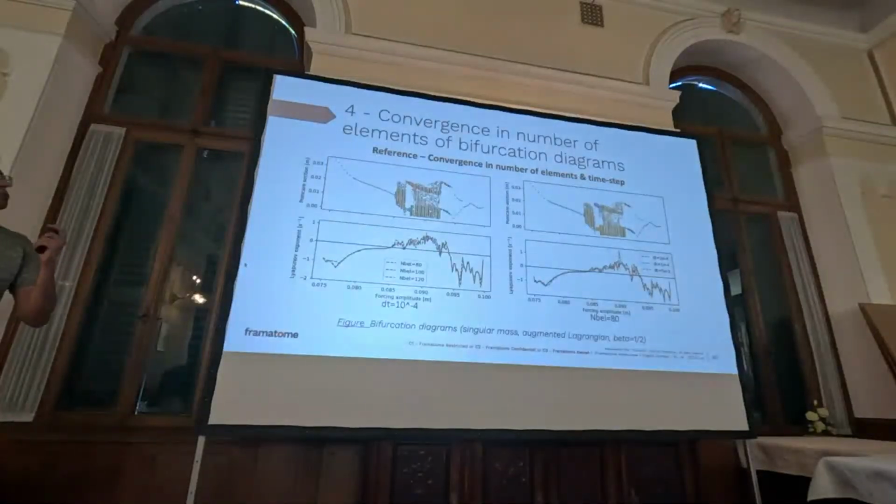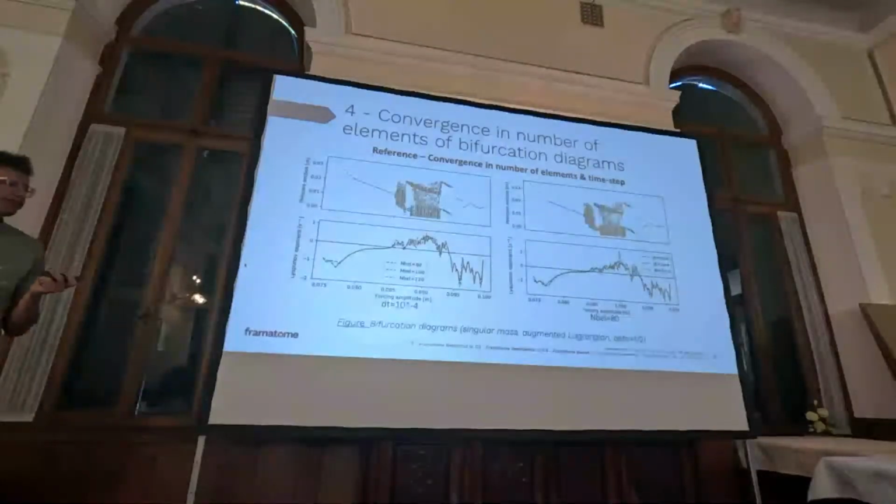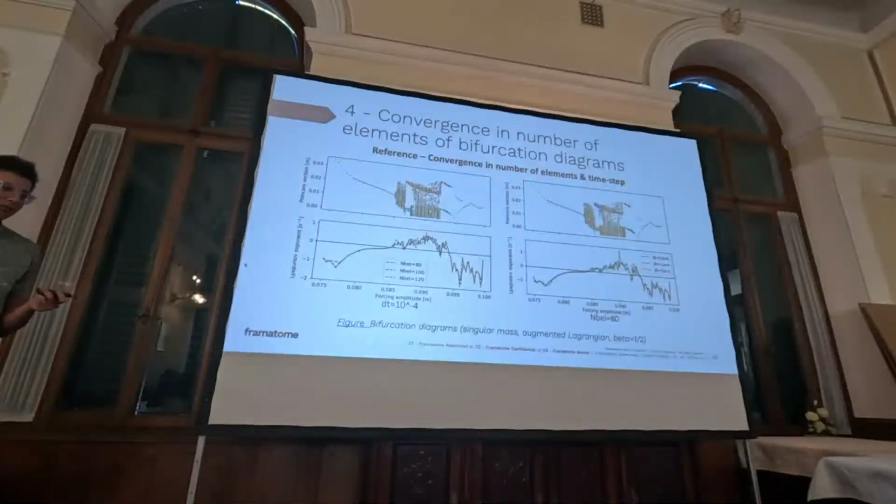So now we go with our reference solution, singular mass matrix, and the parameter of the Newmark scheme beta equal 1/2 that is related to an unconditionally stable solution.